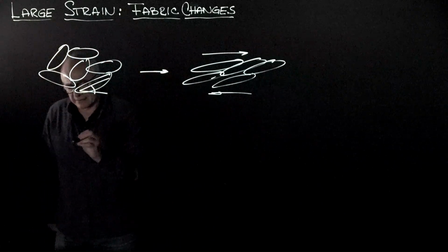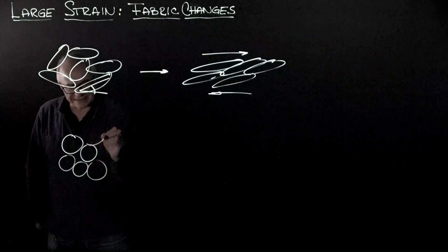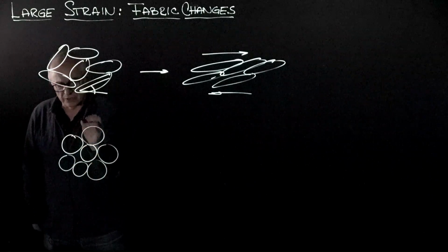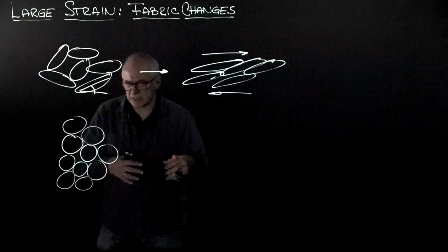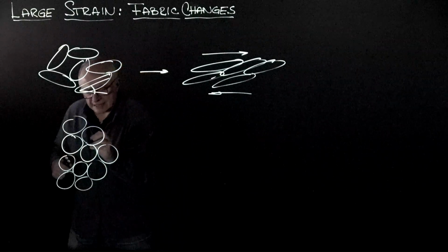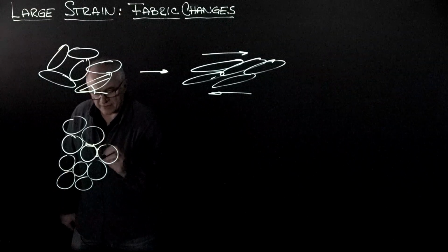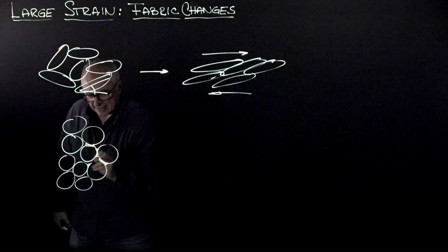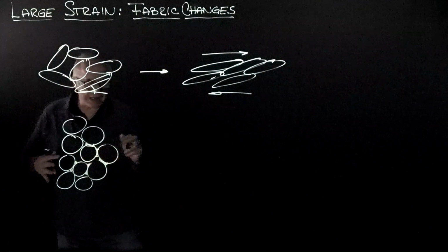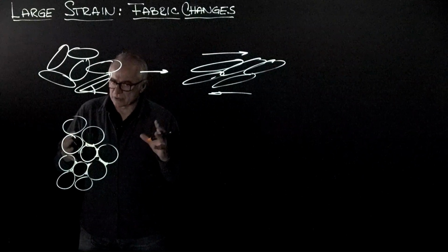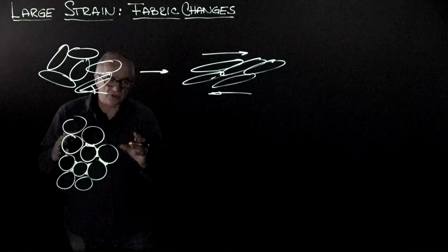The other case is that if you have a soil that is cemented, lightly cemented, we are not talking about a sandstone, we are talking about a soil with some degree of diagenesis, or it has experienced wetting and drying, and some cement forms at the contacts, then this soil behaves quite differently as well. And the reason is that during shear, it tends to break like in blocks. It doesn't totally degrade during early stages of shear. It tends to break as in blocks.